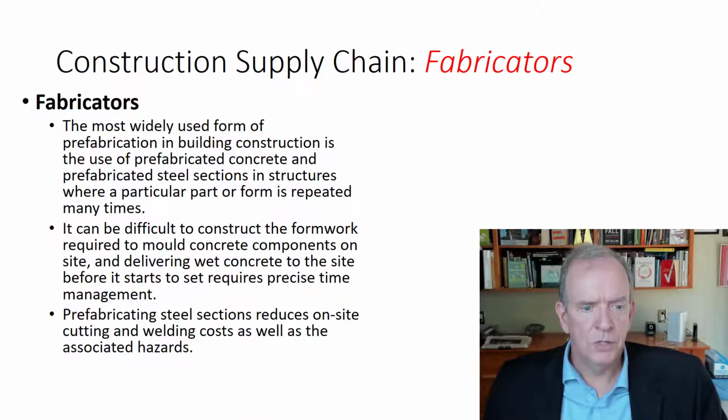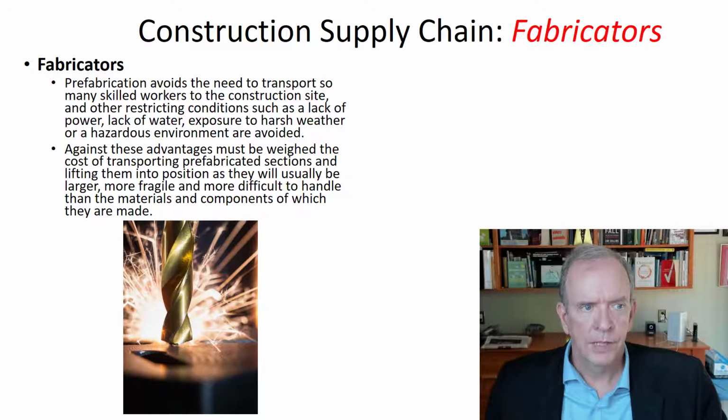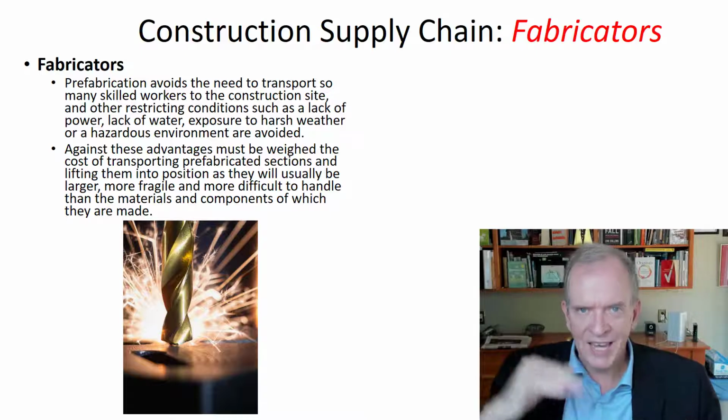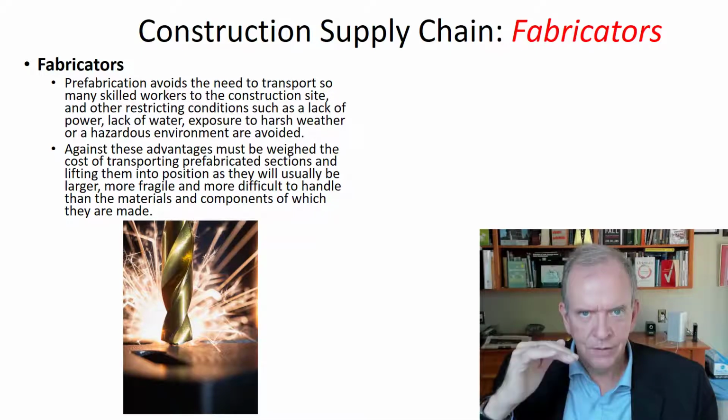So as I mentioned, you can read through the slide and get the sense of that, but definitely prefab has a lot of benefits where it's possible, where it makes sense, right? And prefabrication avoids the need to transport so many skilled workers to the construction site. And the volume of workers sometimes on the construction site, we call it stacking of the trades or stacking of the work.